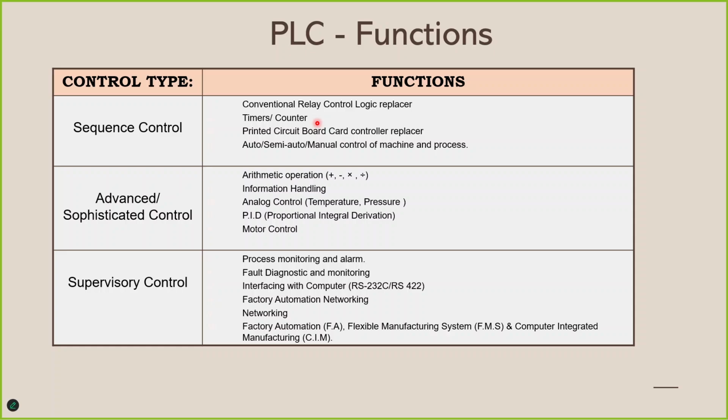The light switches on. The same PLC can then be programmed to say, when you can no longer sense movement in this room, switch off the light. However, wait until 2 minutes to be sure that there is no one in the room. The PLC also can do that. So it has the ability to read inputs, to use timers, to do some counting, and give outputs as well.